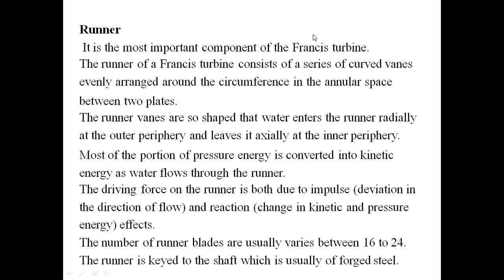Now, runner. It is the most important component of the Francis turbine. Runner of the Francis turbine consists of a series of curved vanes evenly arranged around the circumference in the annular space between two plates. The runner vanes are so shaped that water enters the runner radially at the outer periphery and leaves axially at its inner periphery.